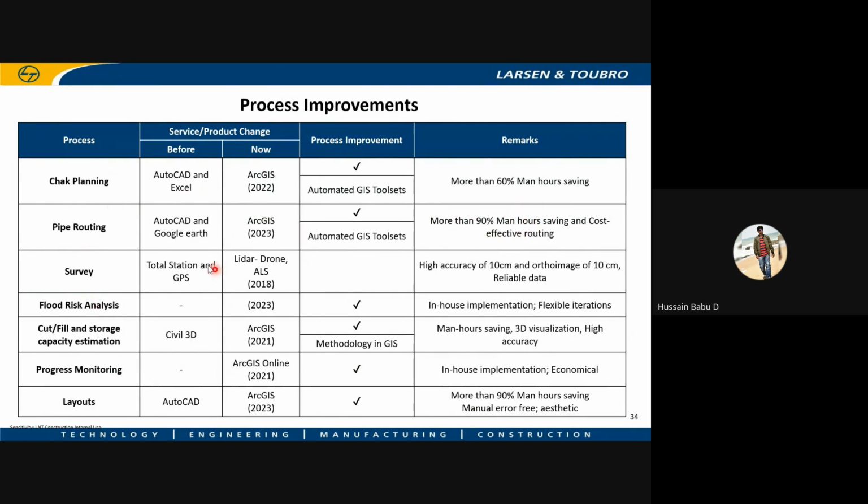For surveys, earlier it was with total station and GPS. Now we are mandating all projects with LiDAR survey, with drone or aerial LiDAR. On flood risk analysis, we are doing it with HMS software completely in-house, which will be explained in the next session by Mr. Ronesh.